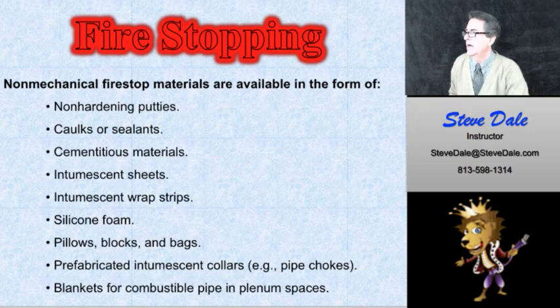It's pretty good, actually. But you really don't need to know a specific type of fire stopping and how to do it. What you really need to know for the exam is basically that if you or somebody penetrates a fire stop, you have to bring it back up to the rating of that particular fire barrier, whatever it is, and it has to be with pre-approved material that is tested and already rated and approved for use.